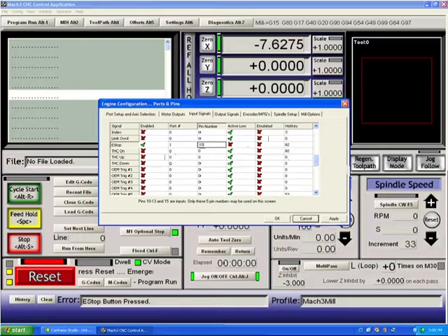Pin 15 would be fairly typical, and will do the job for you. You can see that the active low is checked off. Therefore, a high signal is what is going to trigger an e-stop. At this point, you can pretty much stop using this configuration. Your primary task here in this setup is to get your motors running.